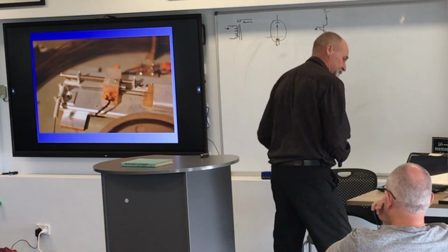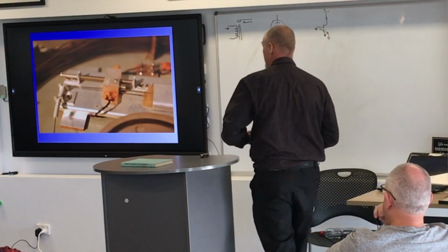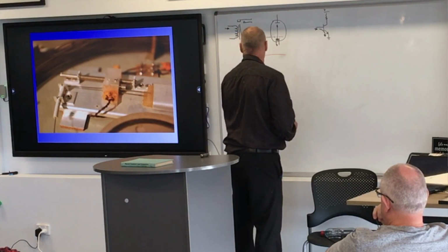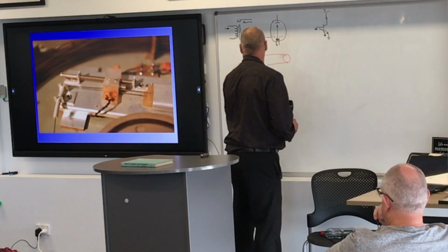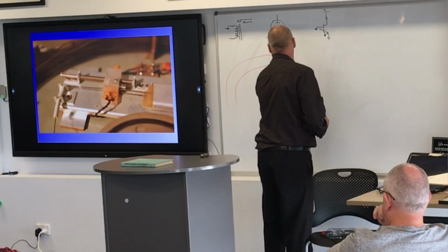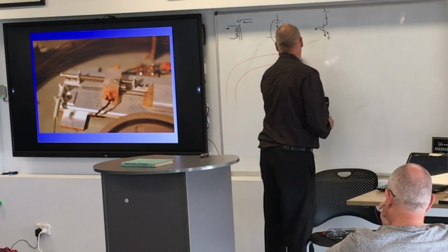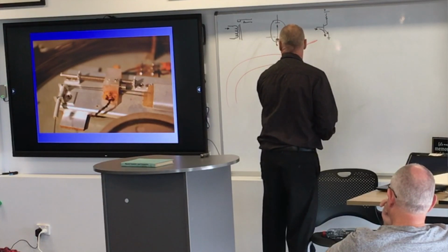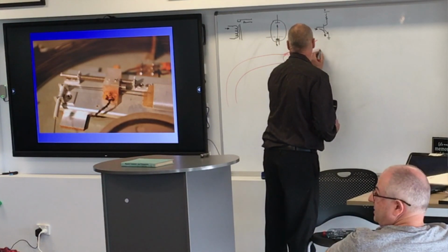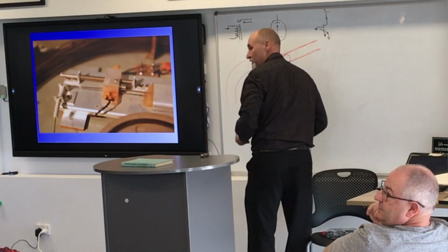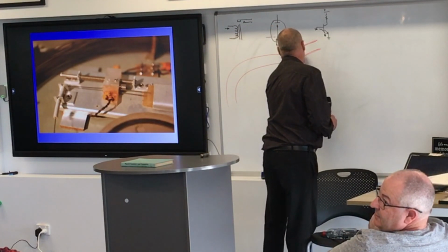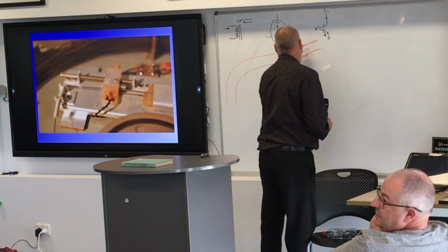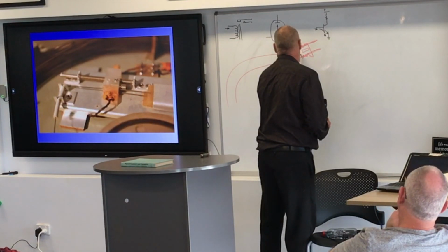And I'm going to just draw what you see there. So there's a big piece of wire flying around, and the cross-sectional end of the wire has really thin, flat nickel straps spot welded to the top. This is about 0.6 of a millimetre, and it's got a set spot welded to the exact opposite side of the wire, and a coil here, and a coil here, and a biasing bar magnet, and it's hooked in antiphase,